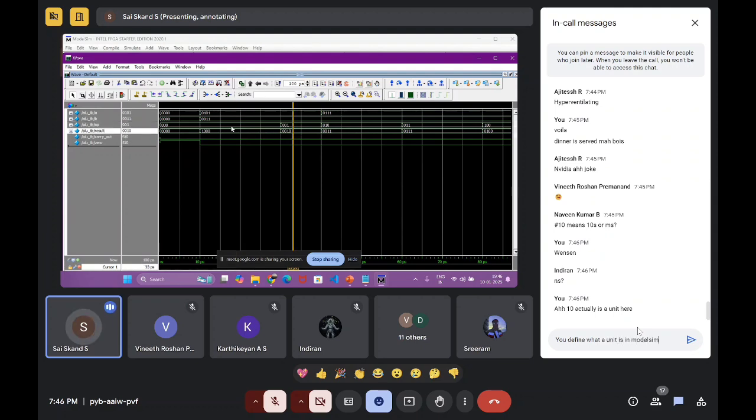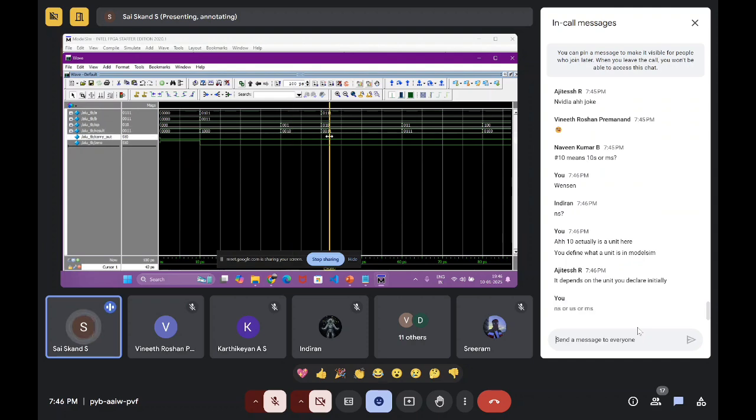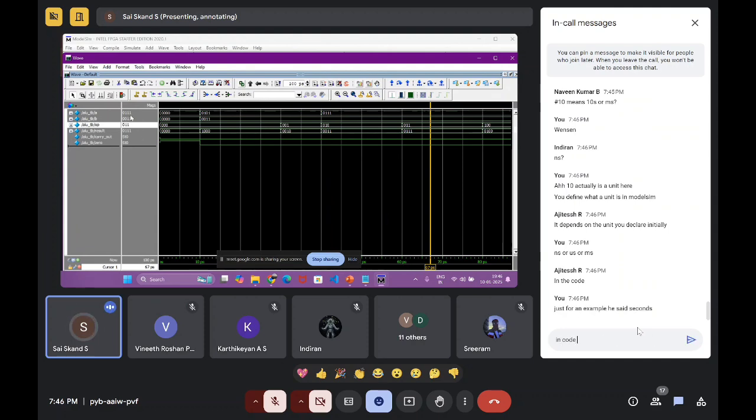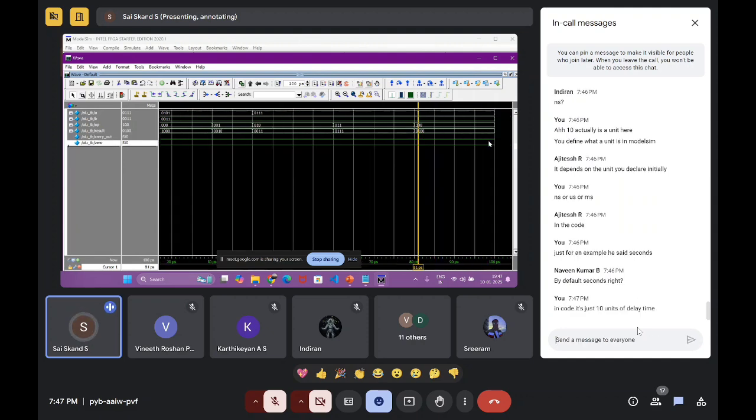Then similarly, for 0 0 1, when you select this, we perform subtraction. 5 minus 3 is 2. So we're getting 2. Similarly, what is this operation? This is the AND operation, we can clearly see. Only when both the inputs are 1, we need 1, so we're getting 1. Similarly, the next operation we can find ourselves. This is OR: whenever any one of the inputs is 1, we're doing bitwise OR. You need to realize there is no carry coming for us. And another operation, what is this one? It's XOR. Only when exactly one of the inputs is 1 do we get 1.